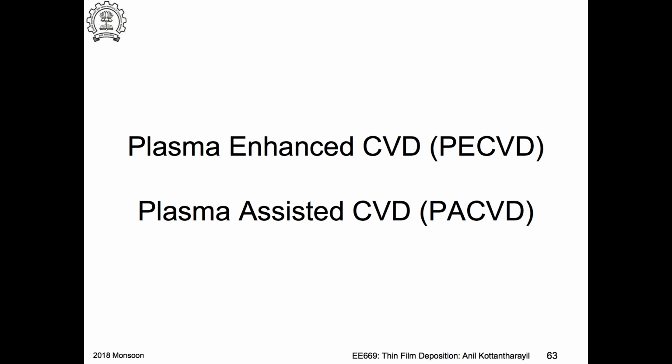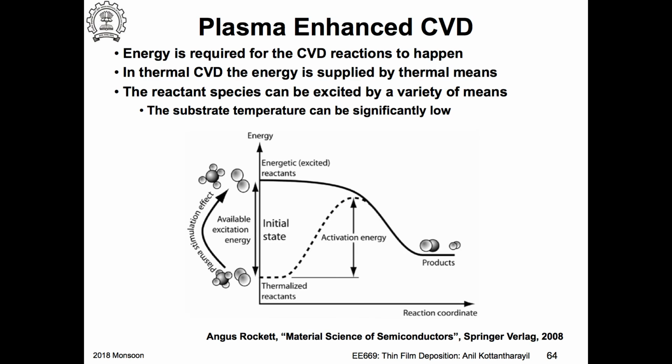Okay. So plasma enhanced CVD helps you in this scenario because you are not heating the substrate to high temperature. You're creating a plasma, so you are counting on the excitation of all these reactants to break them into radicals, ions, and so on that we have seen, right? And they can be excited to higher energy by accelerating them in the plasma. And there are collision processes in the plasma that transfer energy to all these species. Okay, so I don't have to heat my substrate.